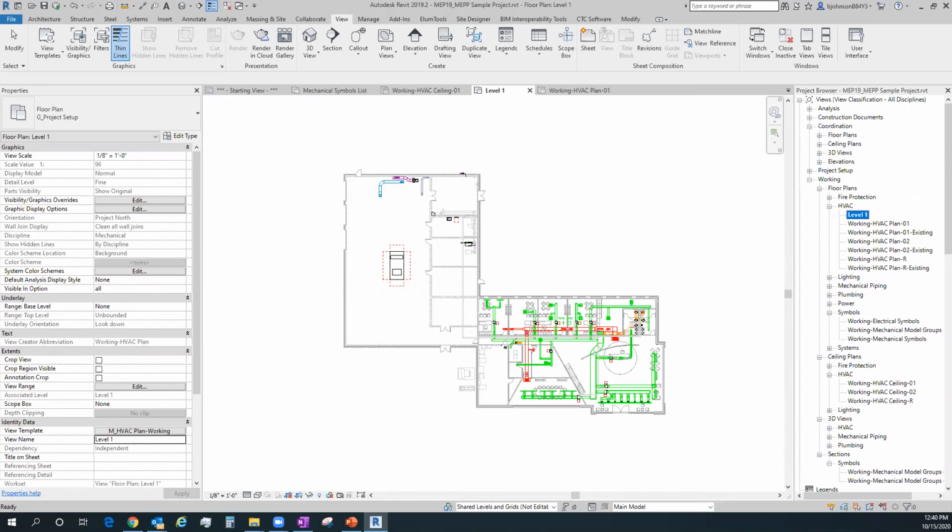And beyond that, other warning types, you need to kind of keep a log if you're the BIM manager of what warning types cause crashes, and you realize that this is a reason for a crash. Keep a OneNote document, keep something, a spreadsheet, whatever that might be as your helper, so that when you're looking at warnings, you know which ones are critical and which ones are just mundane.